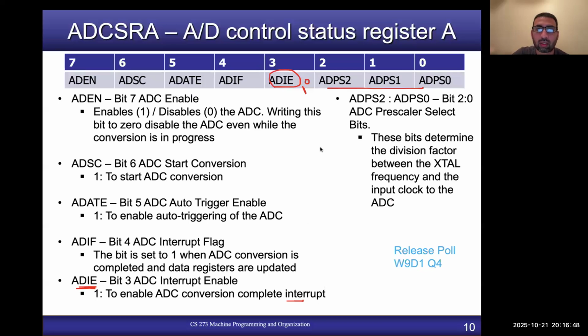Okay. So ADC in Atmega 328P can be used in two modes, right? Which mode? One is your polling mode, the other one is interrupt mode, right? Question 2, polling mode of ADC operation wastes CPU time while interrupt mode does not. That is correct, true, right?